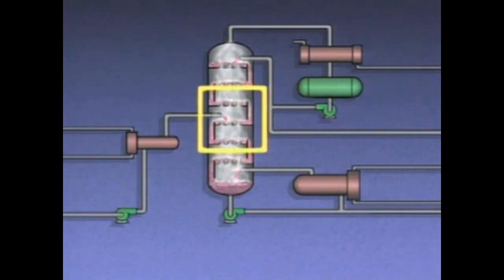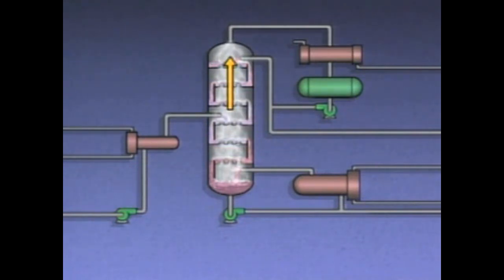Problems can also occur if the feed mixture is contaminated with water or other foreign material. Depending on the temperatures in the column, water could vaporize and contaminate the overhead product, or settle to the bottom of the column and contaminate the bottoms product.